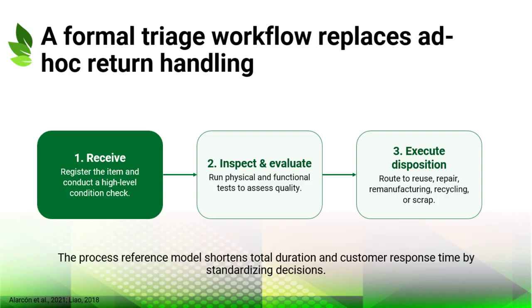A formal triage workflow replaces ad hoc return handling with a clear sequence of decisions. The first step is receiving, where the item is registered and a high-level condition check is performed. The second step is inspection and evaluation, where physical and functional tests assess quality, usability, and recovery potential. The third step is disposition execution, where the item is routed to reuse, repair, remanufacturing, recycling, or scrap.